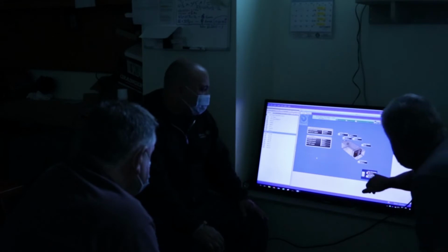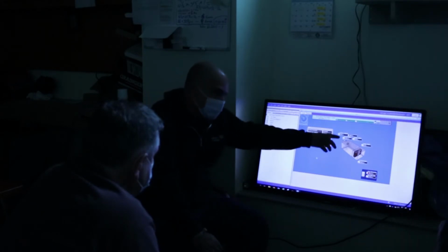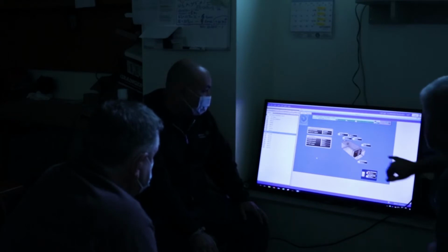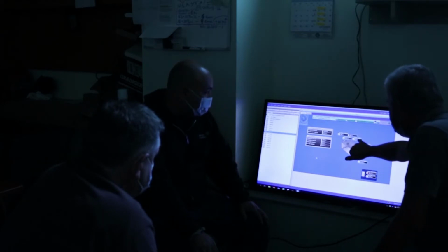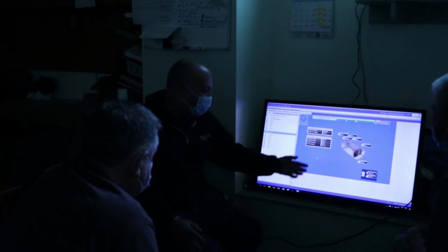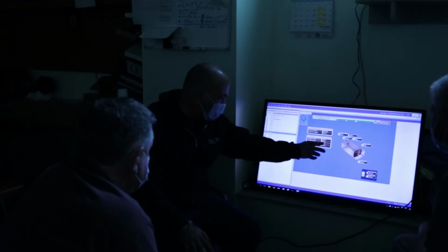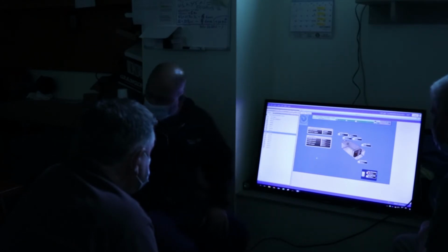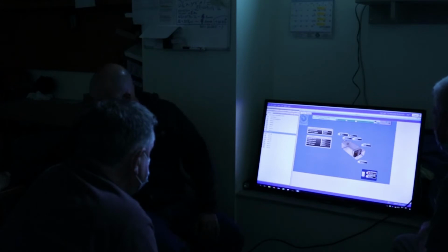Yeah, but the temperature is too high. But that's the max setting. That's how it's balanced. This shows the max setting, because the temperature shows like, well, 65. You have room on it. Percent open. Yeah, but you have room on the damper, but you're at what the balance is, so you're not going to go above that. I don't know if we have a trend on this.